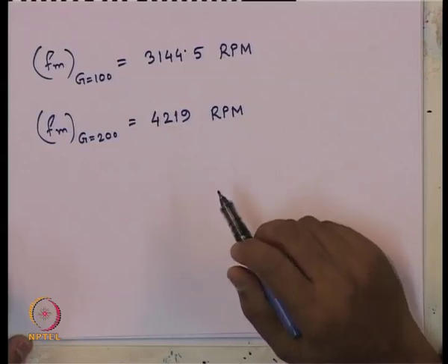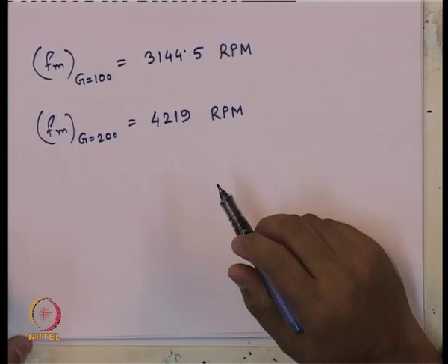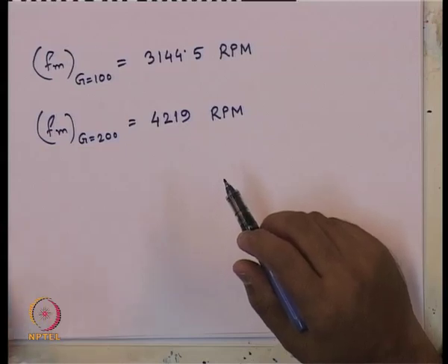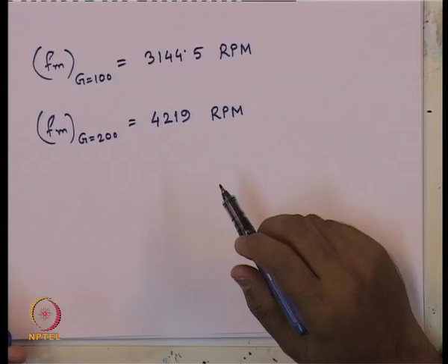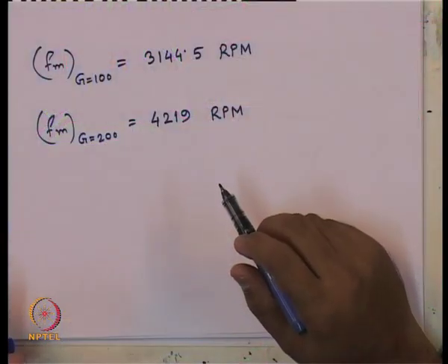So, in torsional mode, the design for all 3 types of soil is pretty safe, whatever the size of the foundation, everything provided, they are very safe, because both the displacement as well as the no resonance criteria are satisfied. We will stop our lecture today here. We will continue further with our lecture in the next class.